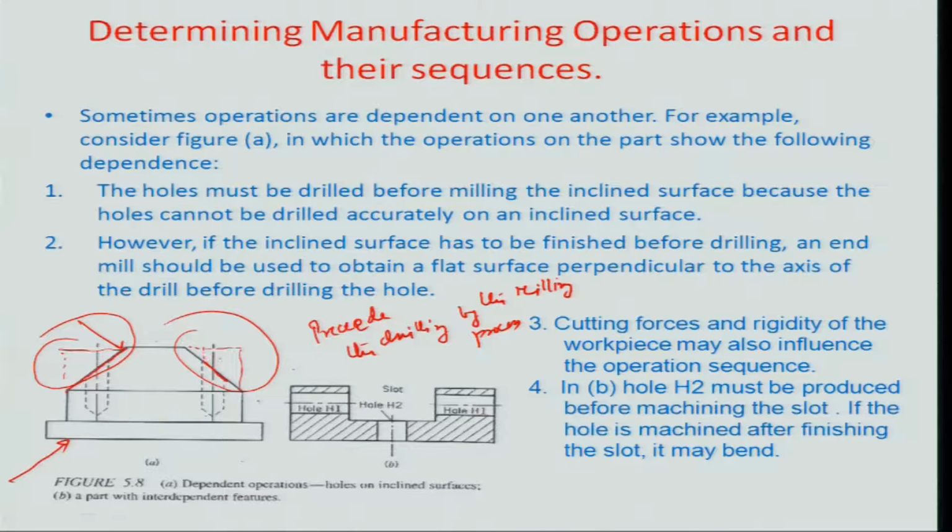If the block were solid and the milling had not been done, and the drilling took place from that particular surface, and later the portion was angularly milled, that would have been a much better operation. So the drilling coming first, followed by the angular milling, is something that gives engineering sense or engineering logic for handling this part.